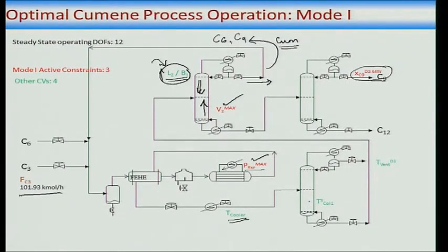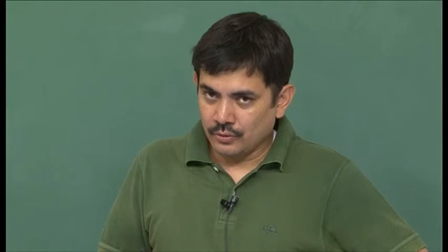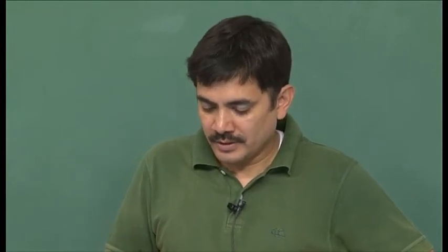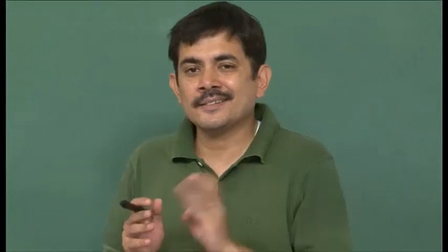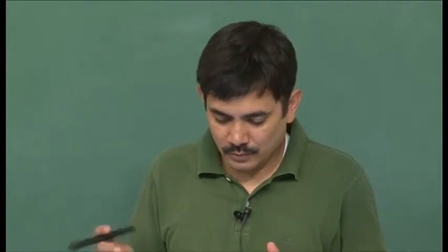And what about the feed cooler? Yeah, well, you want the temperature of this guy to be reasonable, so that all the condensables are condensed, but you do not want too much subcooling, because then this feed is cold, and if this feed is cold, then your boil up here will increase, because to heat up and boil the cold feed will require heat, and the only source is this reboiler. So you want to make sure that you have chosen your cooler temperature properly, so that you are in the two phase region where C9, C6 and C12 condense, and that is about it.